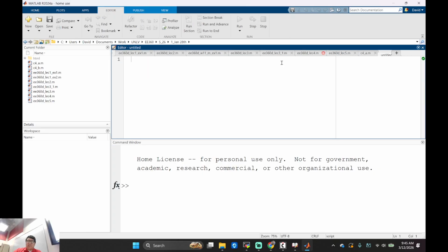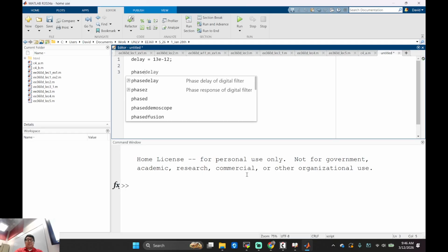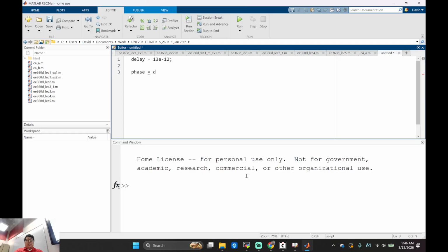Okay, let me see. Here, what's my delay? Delay was equal to what did I say? 13 picoseconds, which is 13e-12, right? And then my phase is equal to the delay times my frequency.